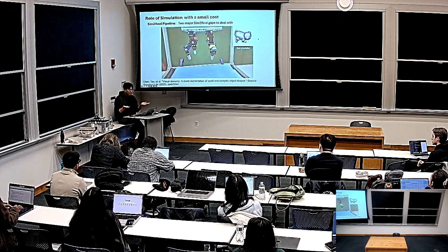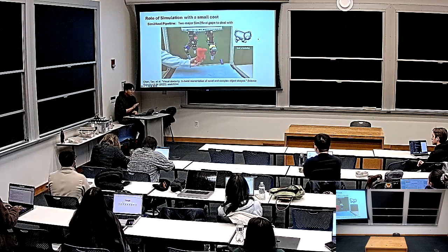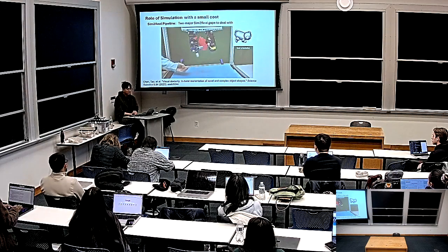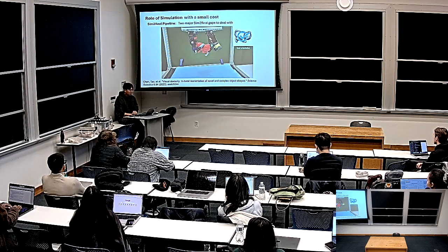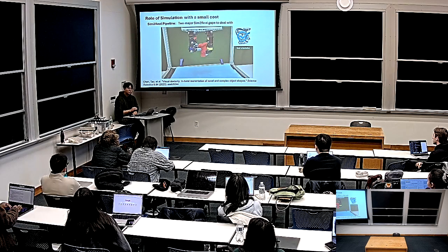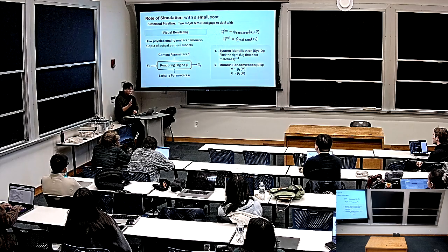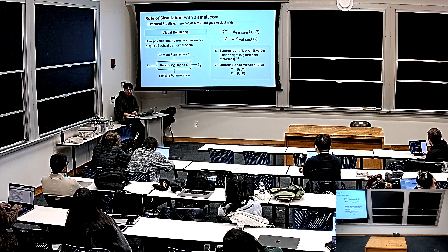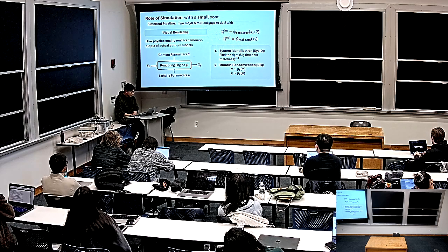Cool. So TLDR, the sim-to-real pipeline that deals with the contact dynamics gap is mostly a combination of both: doing some system identification on certain things and doing randomization on those unknowns. And those randomization ranges are typically based on some educated guesses, like you pointed out before.